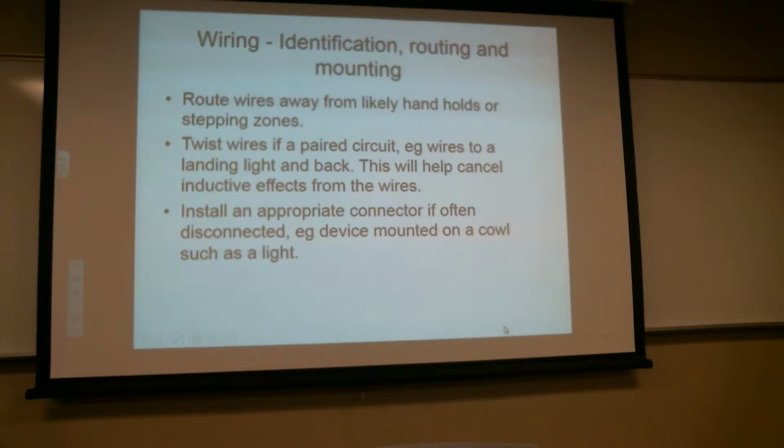I've seen a number of cases where, if I take a piece of shielded wire, single conductor shielded wire, I actually have two conductors, right? I've got an inner conductor and then the shielding to bring everything back. Seen a lot of instances where power goes out and ground comes back. That's the way it was done. I sort of frown on that. Shielding should be used for shielding.